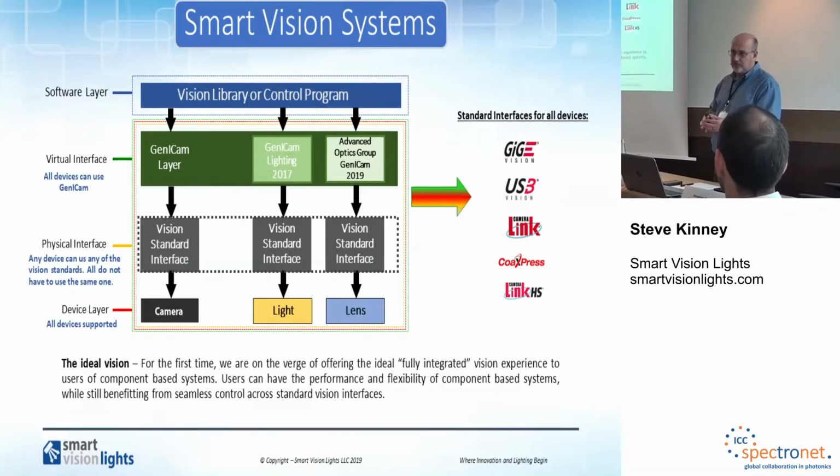And in the optics world, we have things like the P-iris lenses, which are mostly for security, but a P-iris lens is actually a digital lens with a little brain in there and stepper motors to control the iris and work smartly in security cameras. This, again, is not what we need for machine vision, but the point is those manufacturers, this Advanced Optics Group, already have the technology to put the little brain in the lens and put stepper motors on the axes and manually control them in a way that would be interesting for machine vision.